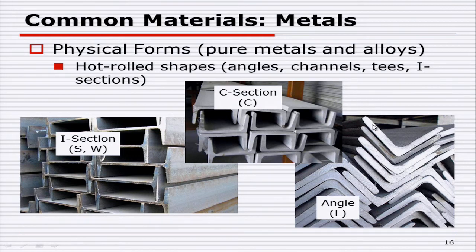These come in different thicknesses. Like I mentioned, 1/4, 1/8 is very common, 3/16 is very common. It's common to get them in 1 by 1, 1 by 2, 2 by 2. Those are very common sized angles, and they would stock those at Wiedenbeck. When you start getting into C sections, they're pretty restricted in terms of what they would stock, because that's not a common order. You've got a thickness to it, you've got a width, you've got a depth. Same thing with I sections.